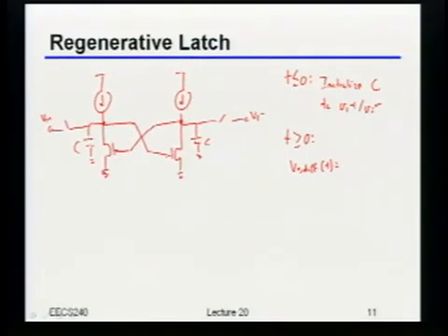Yeah, it will be exponential with GM over C. So it's e to the t times GM over C. There's just one factor that I needed to put in front of this thing. Is it negative? No, it's not, right? I put it in positive feedback. It really does grow exponentially with time. There's just one other thing that I need in front of this.